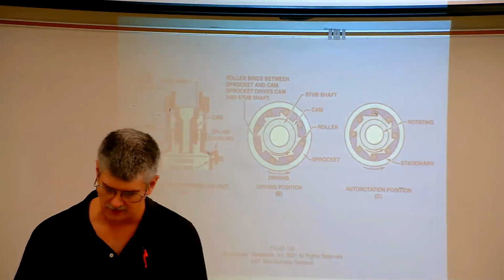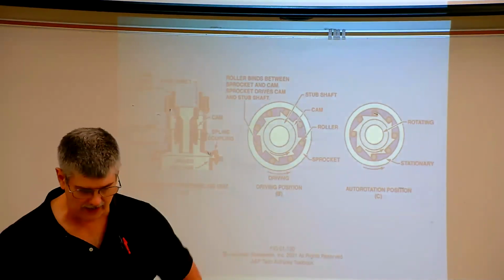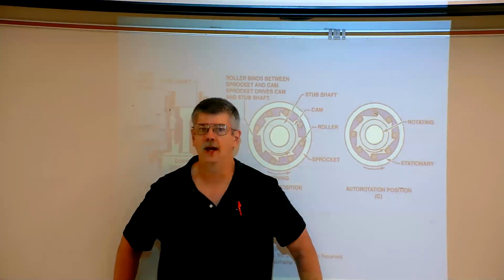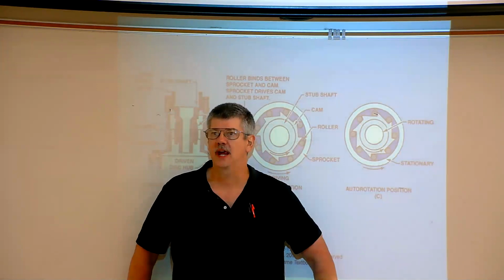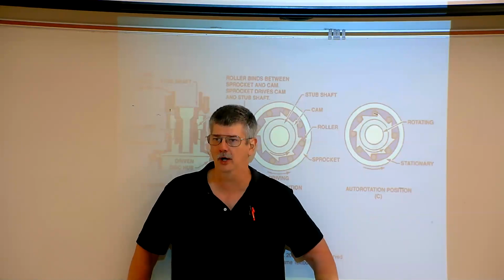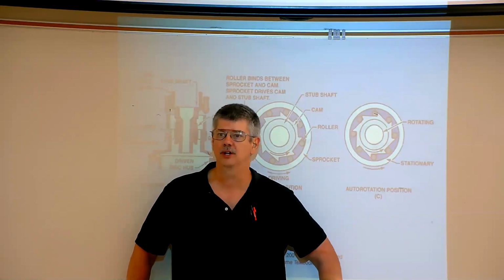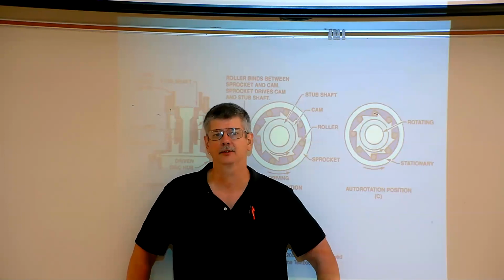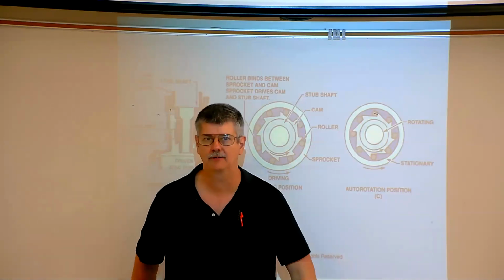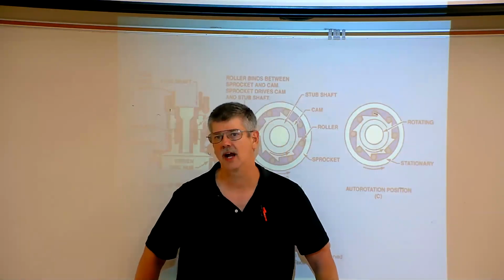All right. We talked about the airfoil sections or airfoils. As we said, if the shape above and below the chord line are exactly the same, we say that's known as a symmetrical airfoil. Symmetrical airfoils are generally going to be used for 3 different types of aircraft. Number 1, rotor blades of helicopters. Number 2, acrobatic aircraft. And number 3, supersonic aircraft.